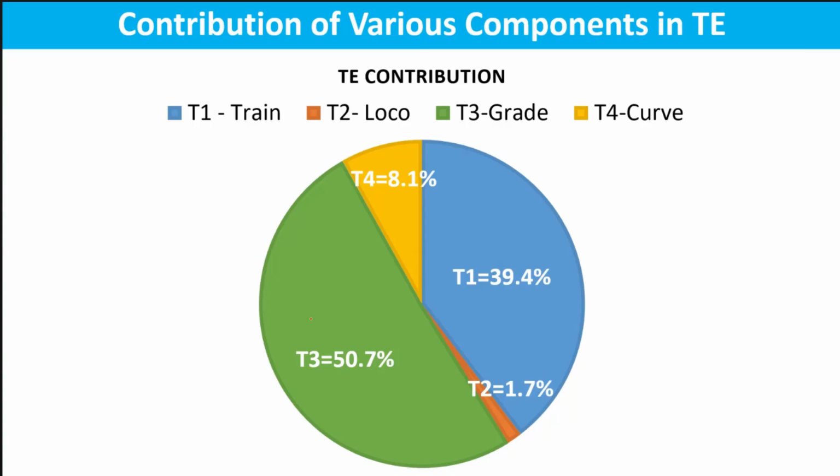of the required tractive effort of a train, locomotive. So this is very important. If the gradient of approach, or whatever the ruling gradient is, is higher, then definitely we require higher tractive force or multiple engines. If our gradient is lesser, then we require less.